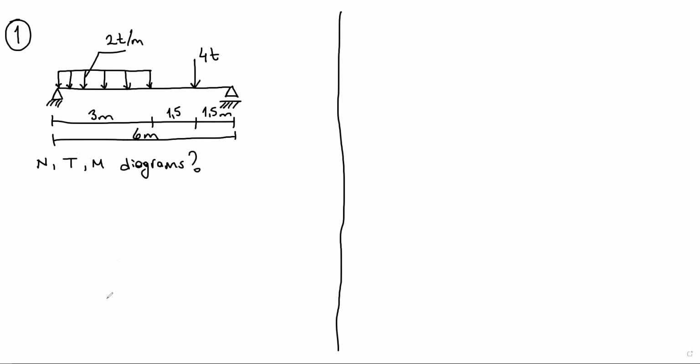Okay, when we have a structural system, what do we do first? Start the internal force diagrams. What should we do first? We have an idea. Maybe remember from the statics course, when we get a structural system, firstly we calculate the support reactions. Okay. We have to calculate the support reactions first.